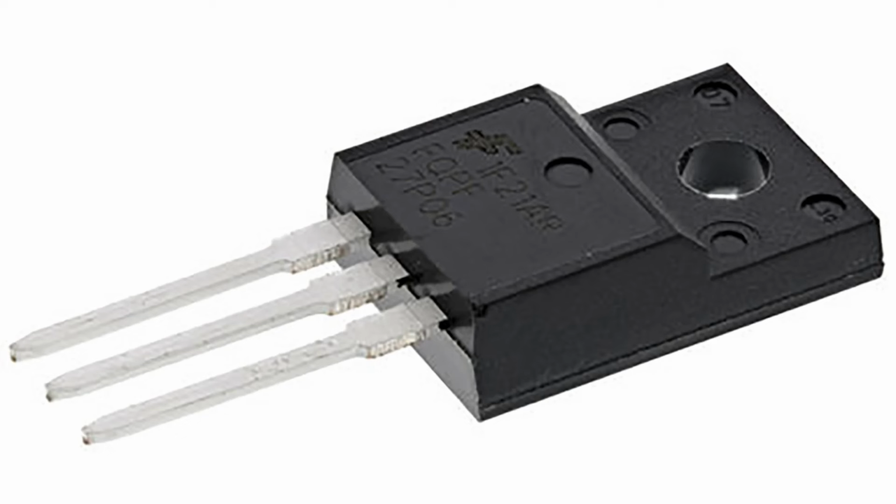6. High current handling capability. Description: power MOSFETs are designed to handle high currents, often exceeding several tens to hundreds of amperes. Implication: this property makes them ideal for applications that require significant power delivery, such as industrial motor controls and power supplies. 7. Body diode. Description: each power MOSFET has a parasitic body diode formed between the drain and source terminals. Implication: this diode allows for reverse current flow in applications like motor drivers and helps protect against inductive kickback.